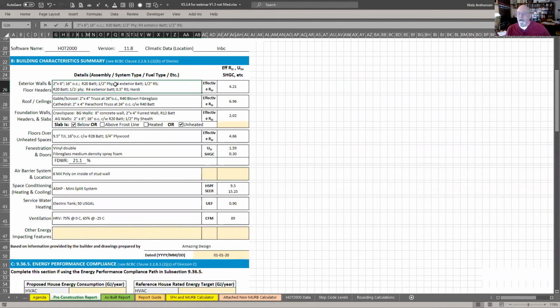And I see drawings that are not modified. We have conversations with the builder. Oh yeah, let's put 2 inches exterior on, or instead of R19 batt, we'll put R22 batt in the walls. We'll put a different kind of windows. The heating systems change, things like that. And that's not noted in the drawings that are put in for permit.